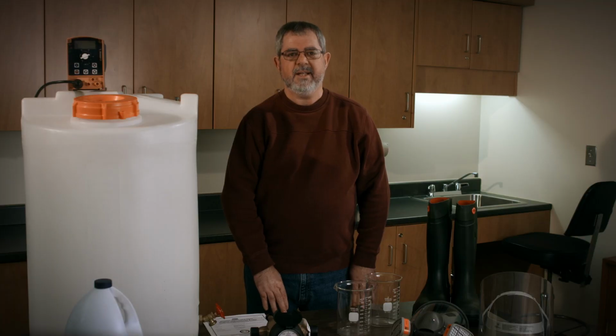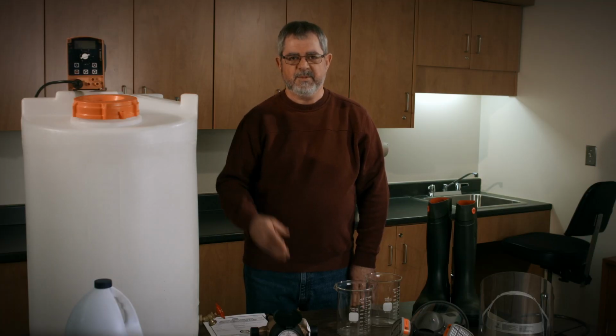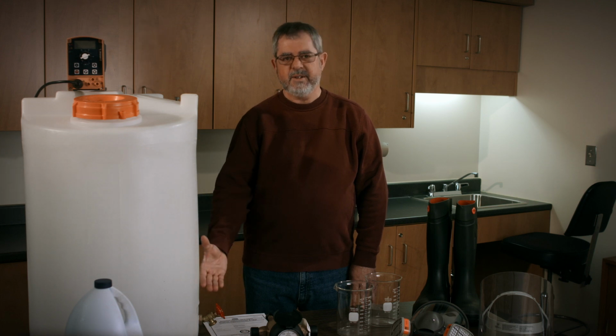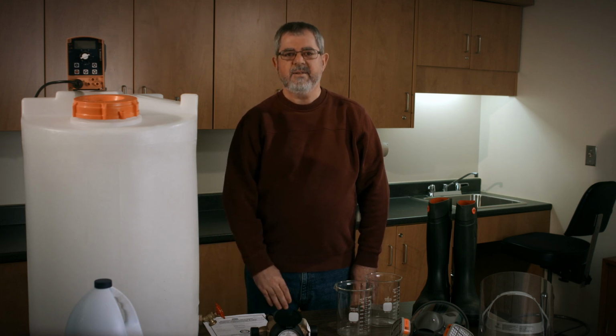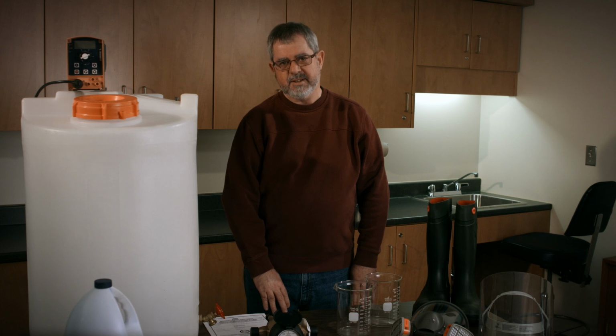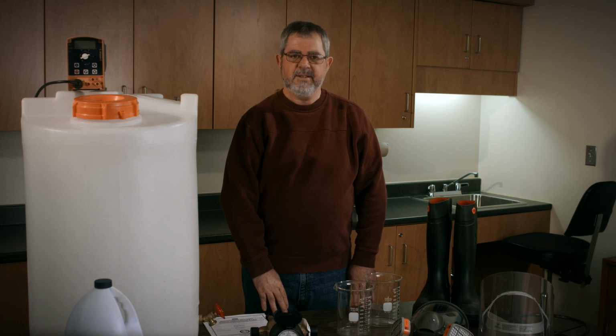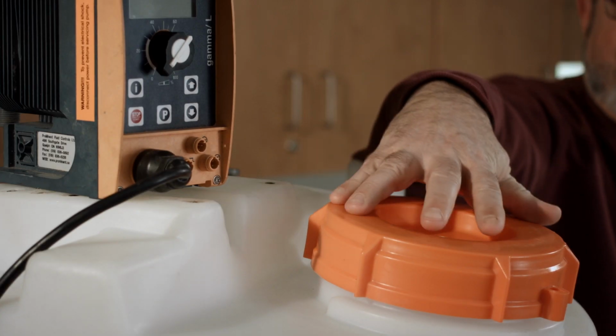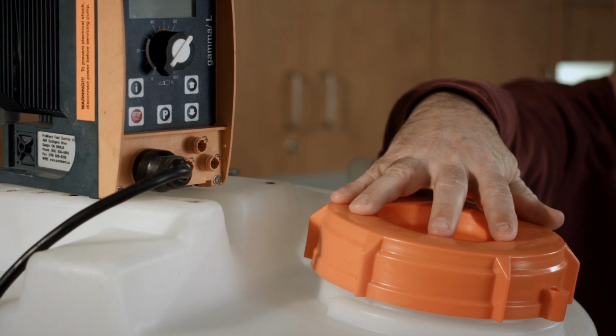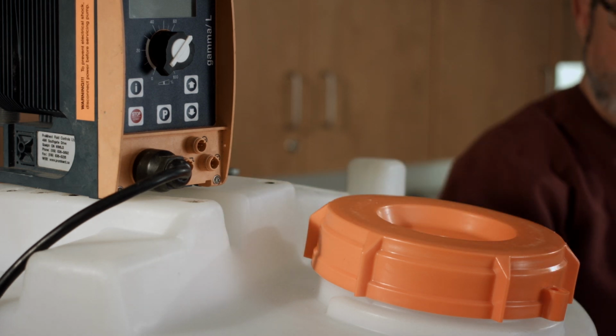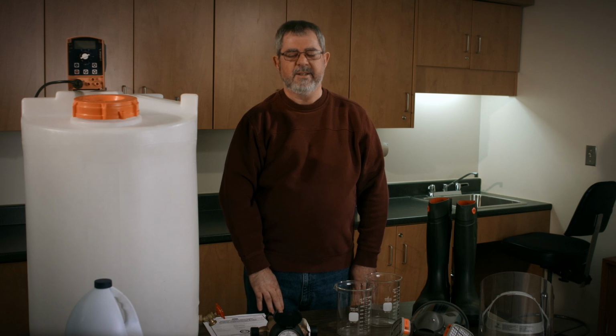The solution tank should be made of plastic such as polyethylene or other chlorine-resistant materials and conform to the NSF Standard 61 for chemical tanks. It should hold at least 1 week's supply and be placed in a cool, dry area. The cover should prevent contamination by dust, debris, and insects. The tank should be cleaned and washed at regular intervals.